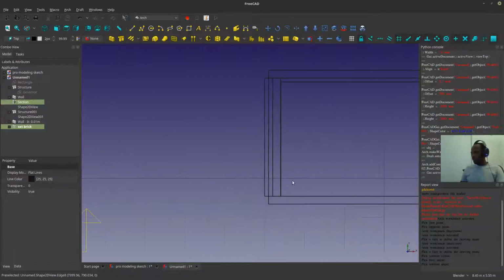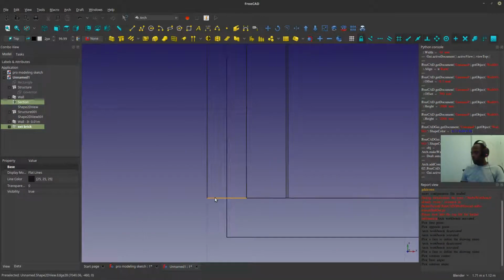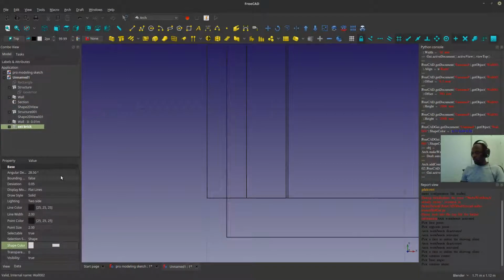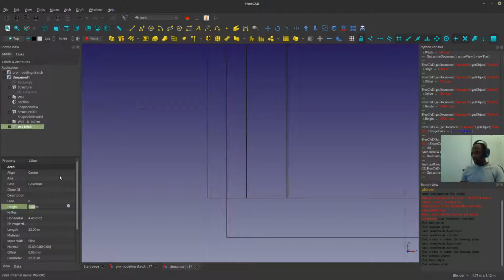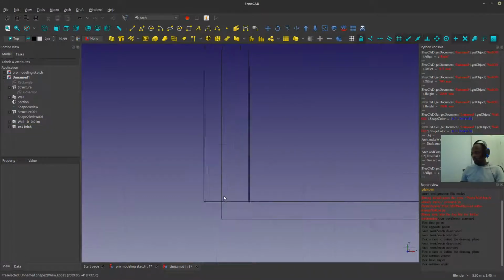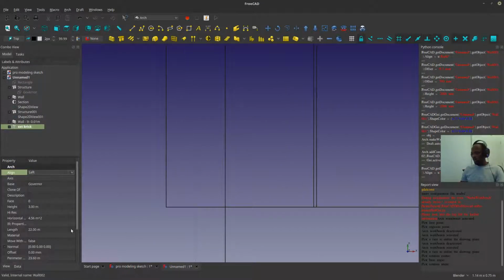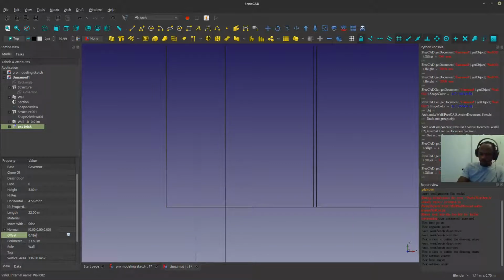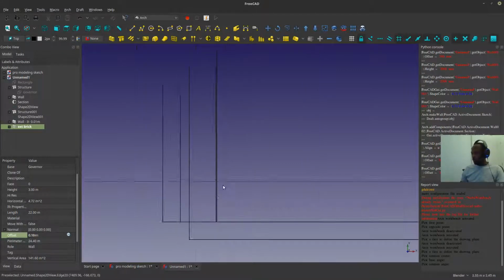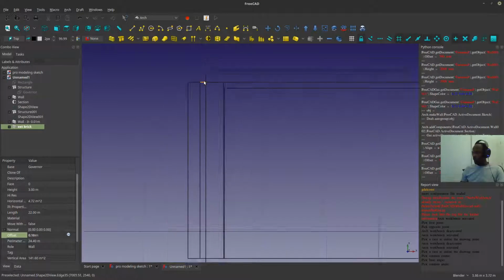So come to the top here, and so what I'm gonna do is align this. I'm gonna tell it to be left align, like this. Okay, but I want to create the gap of space. Maybe that gap is gonna be 0.3 or 0.02, maybe 0.1, 0.1 m. There you go. I have my gap of space.